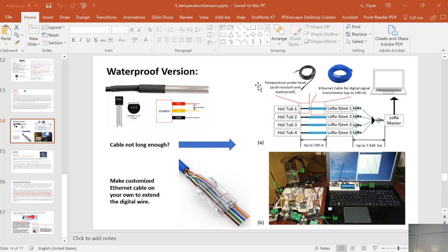So what's happening is it's oscillating so fast, and you have two cables together, or power and ground lines. The signal line is oscillating that fast, and there are so many parasitic capacitors. Even though you do not have caps, the metal traces, the metal cable, and the rubber material outside the cable, and then metal again, is actually a cap.